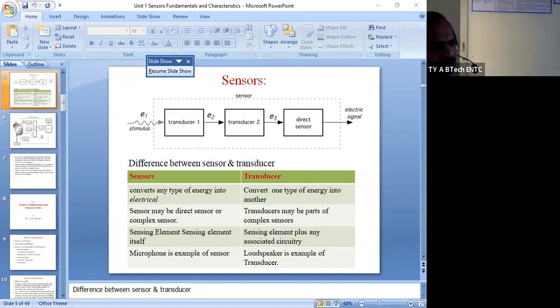So with the help of the microcontroller, we are controlling the actual device, which is a water pump or motor, and the controller only initiates the trigger like turn on, turn off. That is providing supply, removing supply. According to that, it will turn on or turn off the motor. And what is the feedback mechanism for that? Whether it is necessary to turn on the motor, again, level detection. Level detection inside the tank is very, very important.